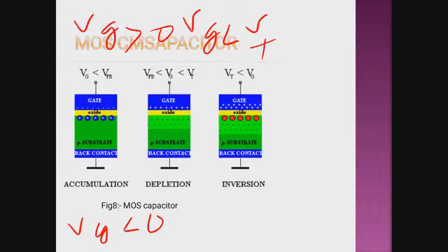So here in this diagram we have seen there are two capacitive effects. One is for oxide, which is denoted by COX, the oxide layer capacitance, and another one is due to the depletion region, C suffix DEP. So if we calculate the total effective capacitance, that will be 1 by C equal to 1 by C oxide plus 1 by C depletion. Why is it 1 by C?